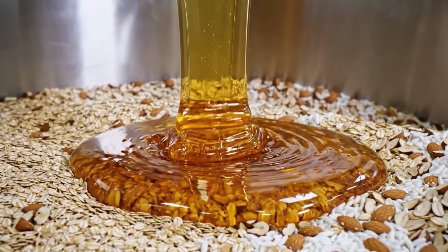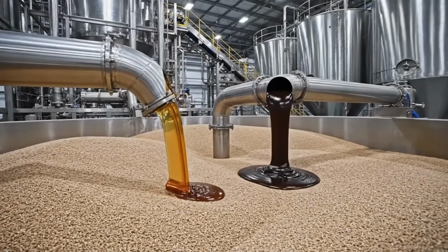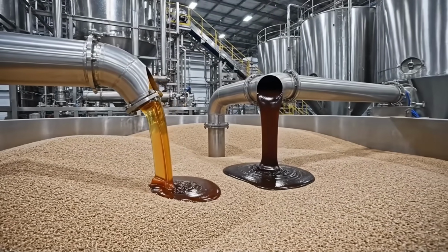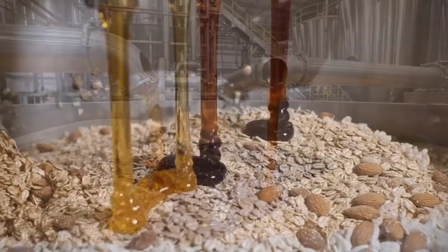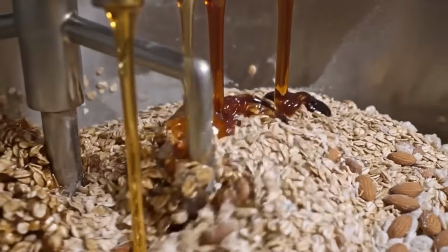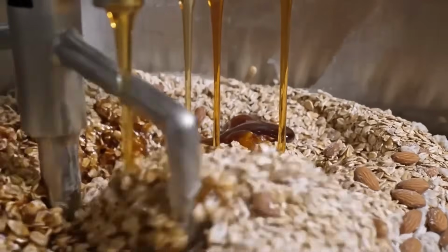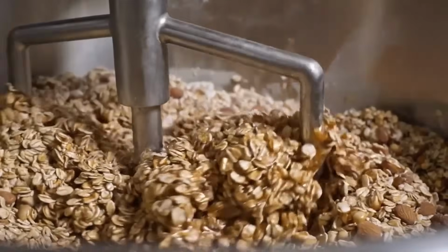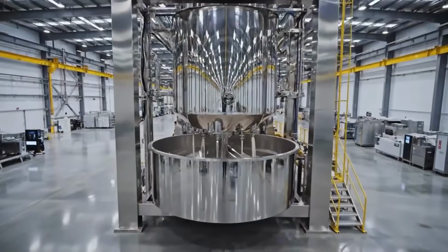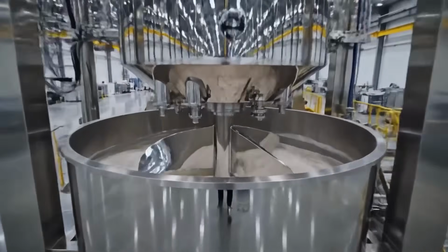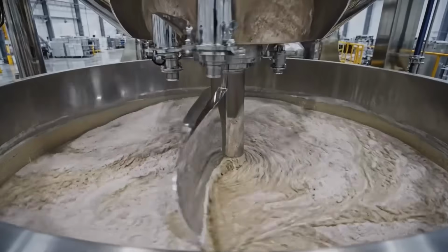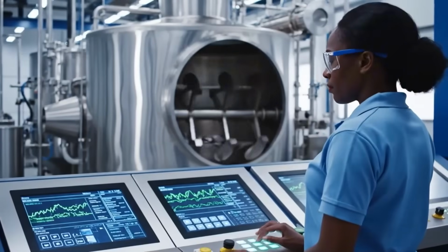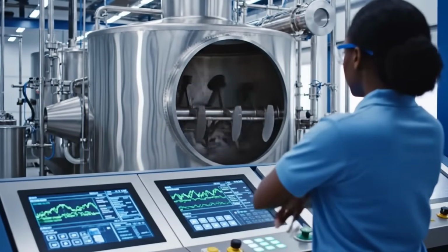Dry blending begins with oats as the primary structural phase. Oats are loaded into a ribbon blender or a paddle mixer. The mixer runs at low speed to avoid breaking flakes. If nuts or seeds are included, they are added and distributed. Dry powders, such as protein, are added as a pre-mix to reduce streaks. The dry blend is mixed only until distribution is uniform because overmixing generates fines.